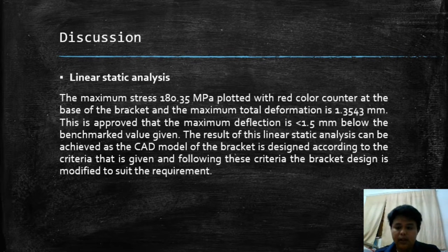Next, I will be presenting about discussion. First discussion is linear static analysis. The maximum stress, 108.35 megapascal, is plotted with a red contour at the base of the bracket, and the maximum total deformation is 1.3543 mm.